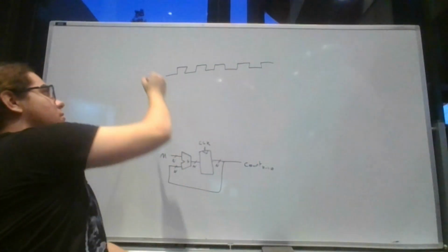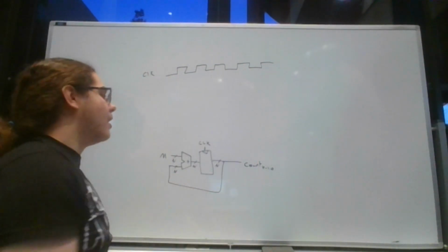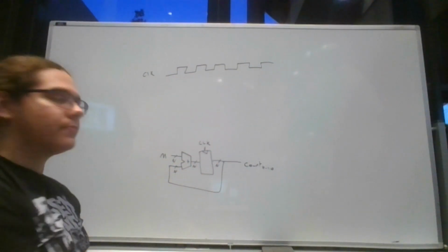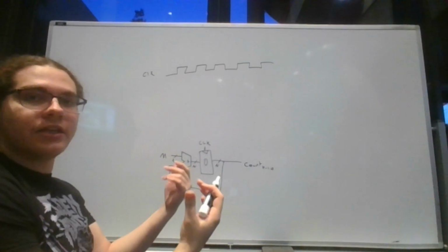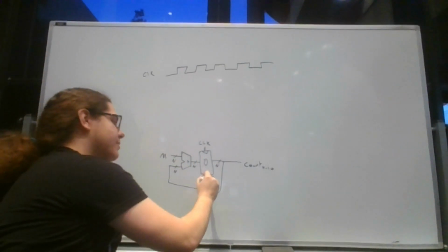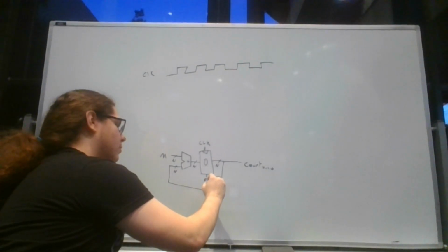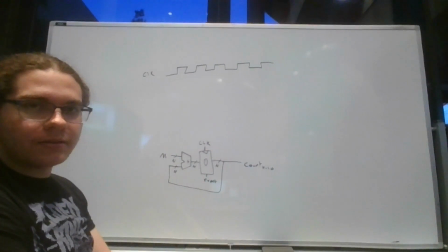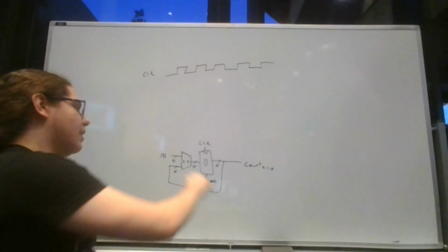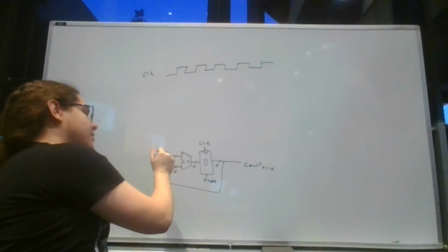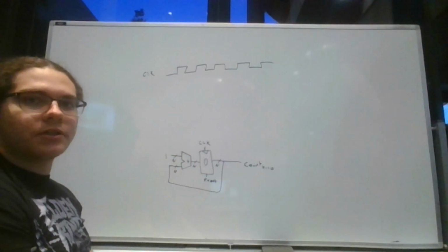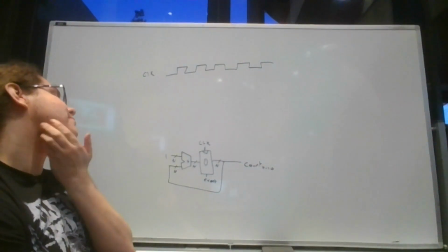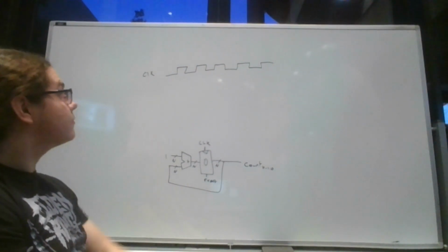So I have my clock signal, call it CLK, and we have to ask ourselves what happens as this clock signal progresses to my register. So the register starts with an initial value of 0. Let's just say that we had a resettable flip-flop and that we were running this on a test bench, and we pulse the reset signal, and now we're measuring what happens right after. And just to make my life easier, let's say that it is 1 on the input of the adder. And so here's what happens.